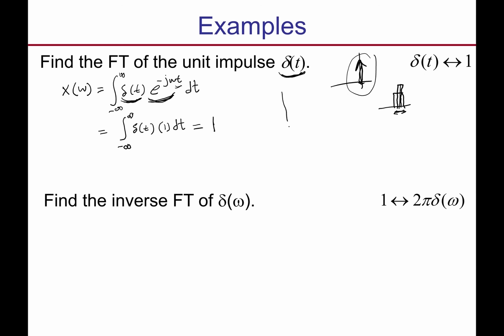If I plot it, that's the frequency content, and it's just like this. That means that impulse, this little thing here, has all frequency content. And that's why they use the impulse to find the impulse response of the system, h of t. Because the impulse has all frequency content, you will know how the system responds to all kinds of frequencies that are present.